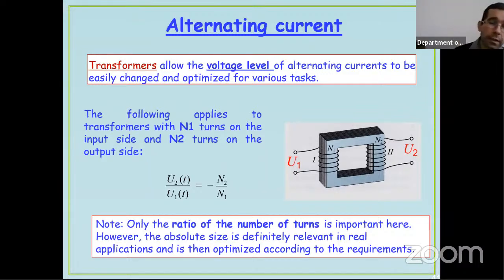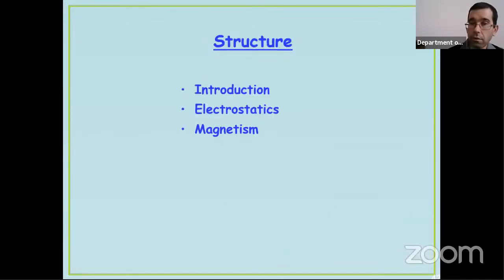If we connect a voltage to the first, primary coil, then we get another voltage from the secondary coil, and the ratio of the voltages is the same as the ratio of the numbers of turns. So that's how we can transform the voltage up or down, how we can make larger or smaller voltages from a given voltage. This is also how your phone charger adapters operate.